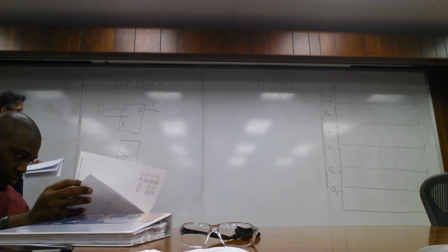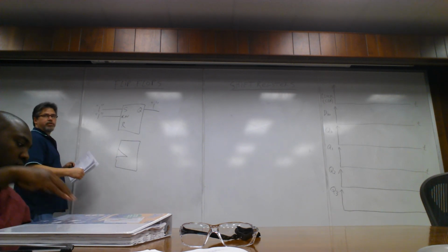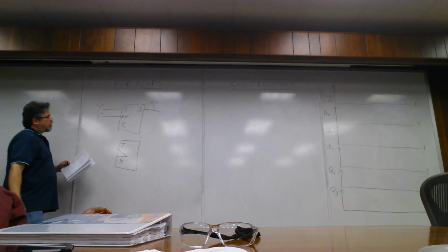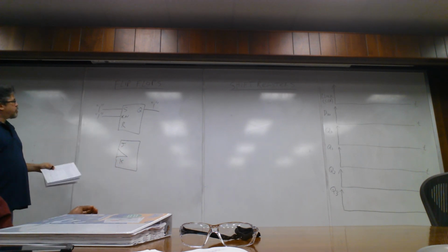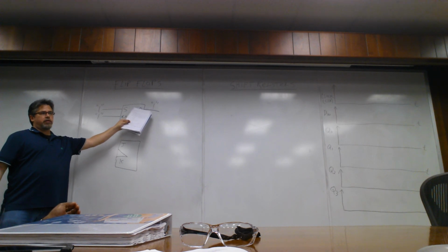And then the JK edge triggered device is considered a flip flop because it moves in sequence with the clock. It responds with the clock, and specifically the edges, the rising and falling edges. S is set, R is reset? Yeah, set and reset. So if we set the bit for 1 and we have an enable 1 here, we're going to have a 1 on the Q, the response.